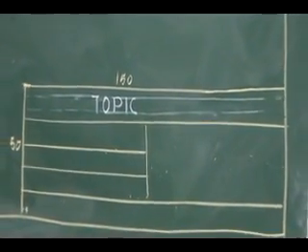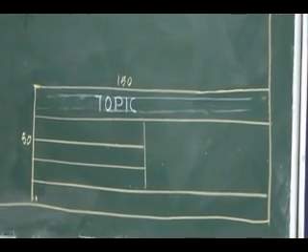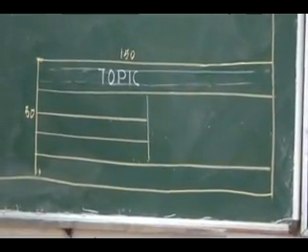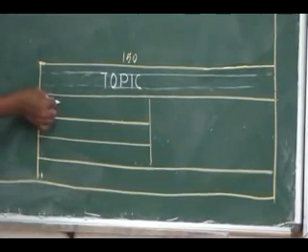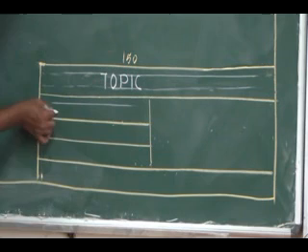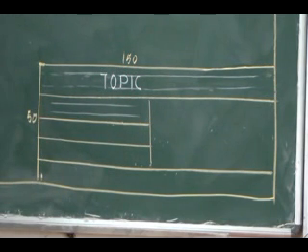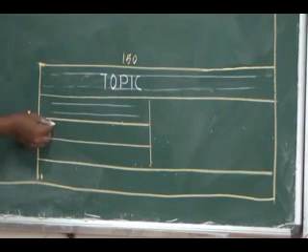Which you are going to write, inside you have to write. For writing letters, we are going to see the standards. Then similarly, the next box you can draw. Again, similarly, you can draw parallel lines for 5 mm height. The box height is 10 mm, so inside, in the middle, exactly, you need not measure it. Always exactly in the middle, in the sense 2.5 at the top and 2.5 at the bottom, in the middle you should have a 5 mm, two parallel lines. So here you can draw two parallel lines.